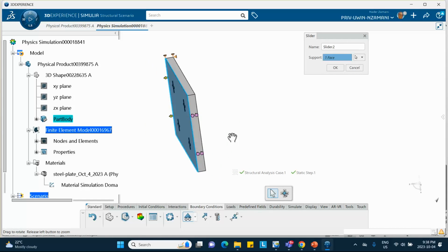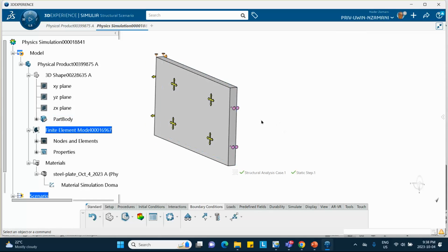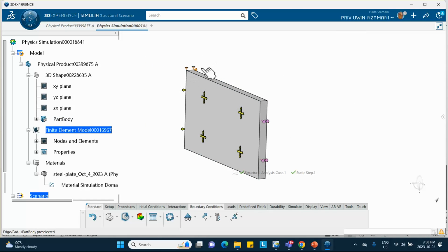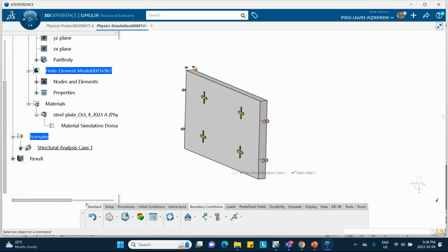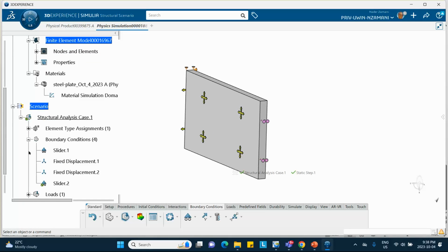Okay. And there. Now, because these are on surface sliders, this thing cannot go sideways anyway. The only thing that I have to do is restrain 1 point from going up and down. I can leave it the way it is, but it's unnecessary. So let me go to the structural boundary conditions. This one I'm going to delete completely. That first one I'm going to delete.